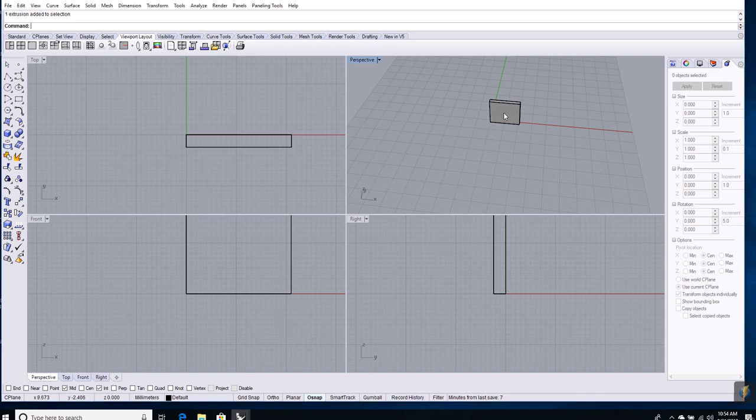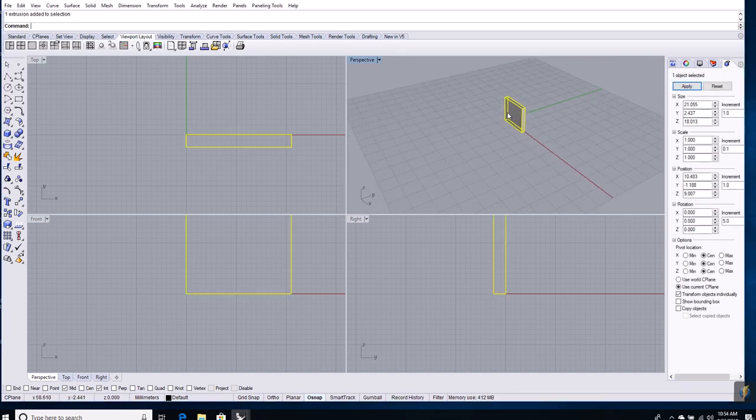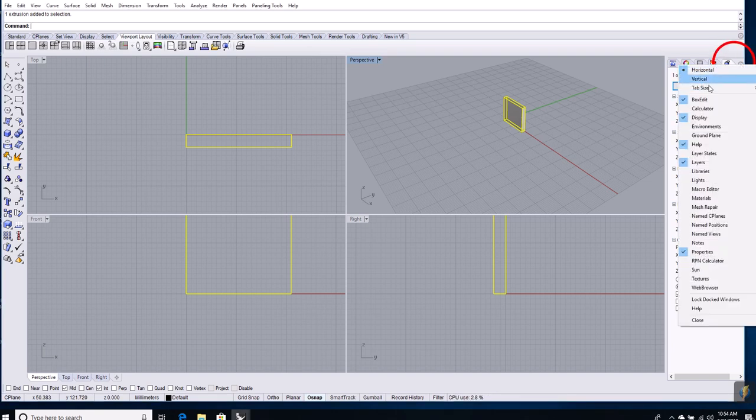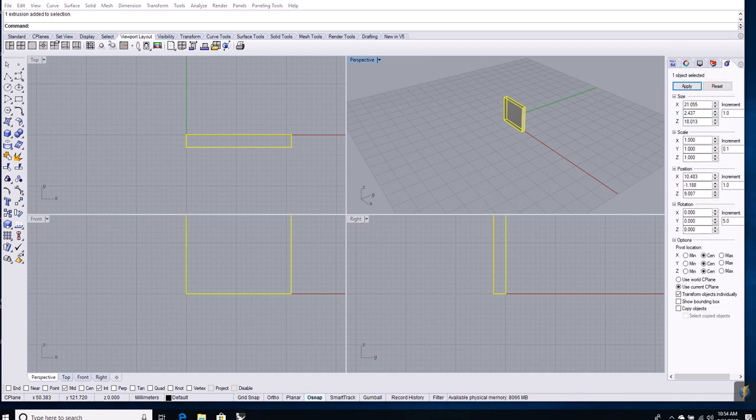So this cube that I made, it's not symmetrical. For the project, you want to make a 50 mm cube. So one of the things that you're going to learn how to do, you have to learn how to do, is using numbers, entering numbers to create the dimensions you want. And the way to do that is there's a box edit tool over on the right side. So if you look at the gear icon and you click it, you'll see there's this thing called box edit, and it gives you tools for changing the dimensions and the position of a lot of the geometry you're creating.